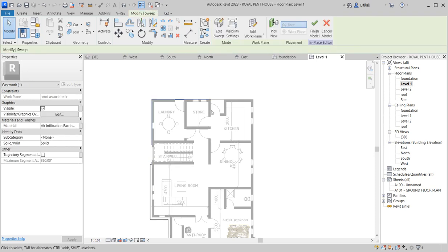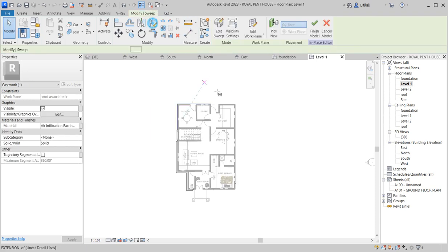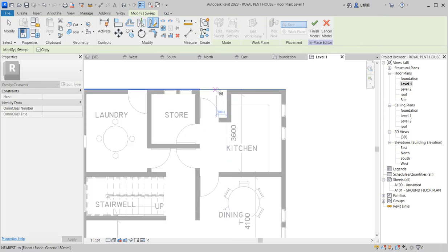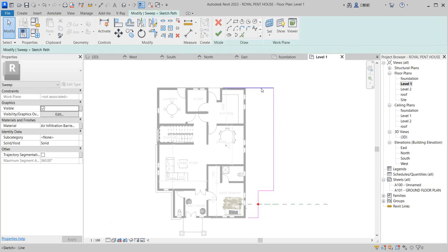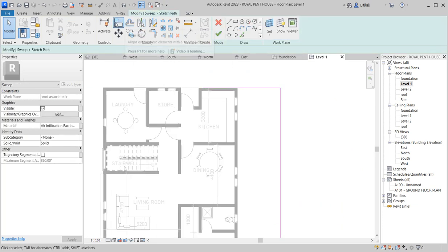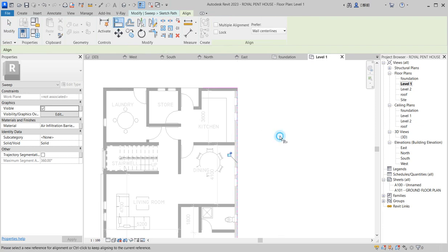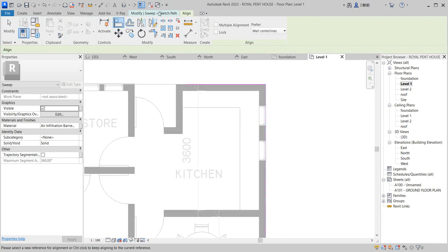You finish it again. This one now you mirror so that you'll be able to go around again, because you cannot draw and close this opening side. So edit that and say edit sweep, edit part, align the parts to the closeness of this. What you do is select this and let it come close.